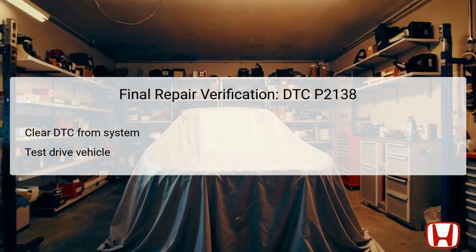Once all troubleshooting steps have been completed and repairs made, it's essential to verify the repairs effectively. This involves clearing the DTC from the vehicle's system using a compatible scanner or diagnostic tool. After clearing the code, a test drive should be conducted to ensure the vehicle operates correctly under various conditions and the DTC does not reappear.